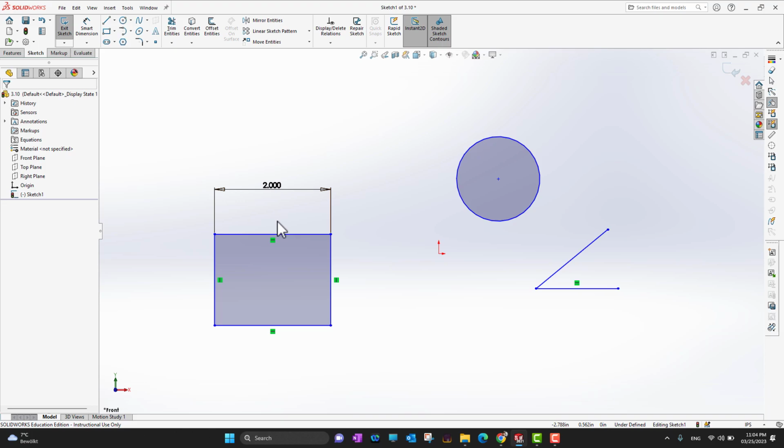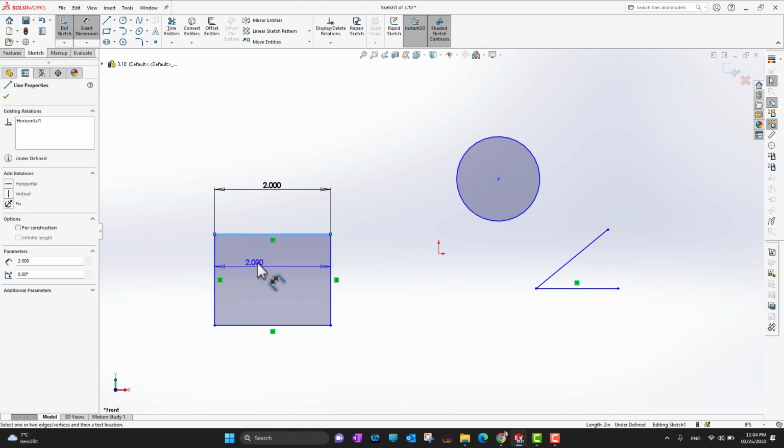And there is another way, which is 3 click dimensions. Again, I'm gonna go into the Smart Dimensions. For the 3 click, if you want to give dimension to this side, you click once here on this side, and then again, because you want to give dimension to this line from this point till here. The first click is here, and the second click you click this line again, and then you can move in this direction, and the third click is wherever you want to insert your dimension.